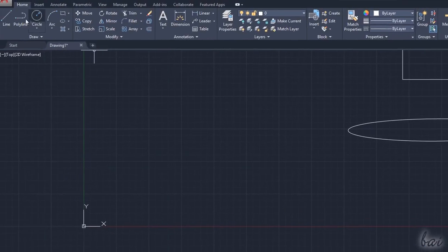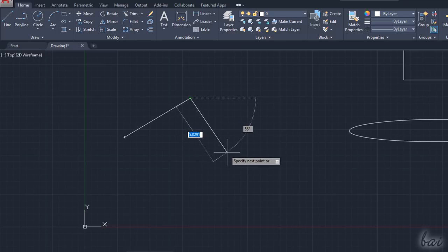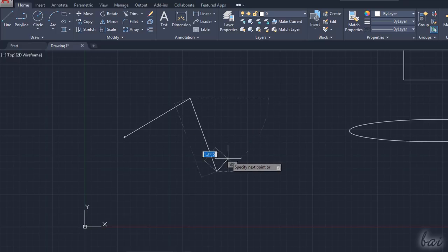You can also make and manage your drawings by using your keyboard. Let's draw a polyline, for example. As you enable the Polyline tool, you can drop the object by using either your cursor to fix the nodes or your keyboard to insert values directly.